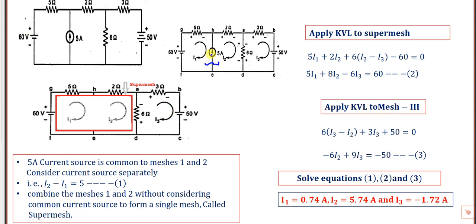See the direction of the current. 5 amps is going upwards. I1 is coming downwards. I2 is going upwards, and the 5 amp direction is mapping with I2, because I2 is going up and 5 amps is going up. So I can directly write I2 minus I1 is equal to 5 amps.